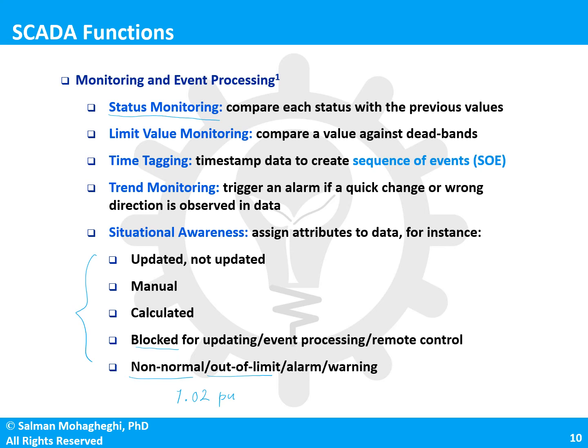In fact, it's quite possible that you get something slightly above 1 per unit. However, if historically in the past 6 months the value of that voltage has always been between 0.95 and 0.99, then all of a sudden the fact that you're measuring 1.02 is something abnormal, and this again can be indicated to you with a quality attribute.